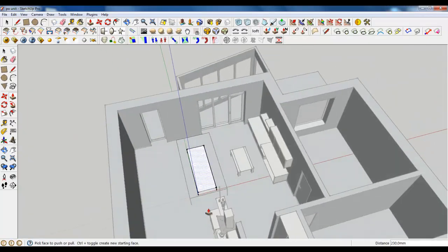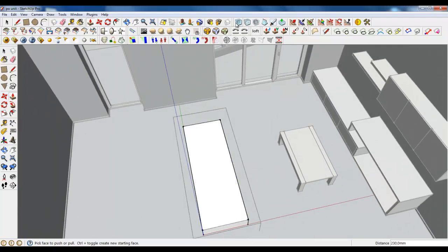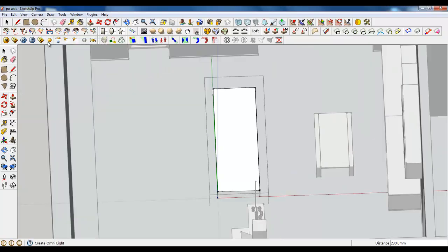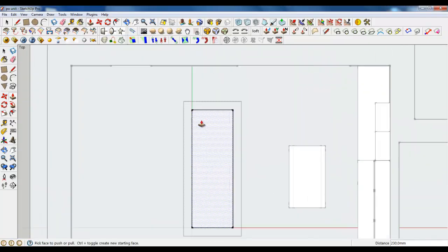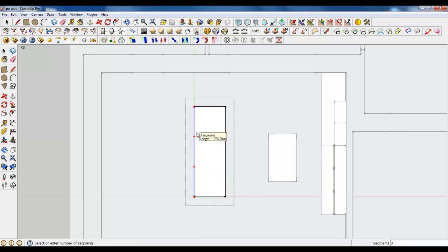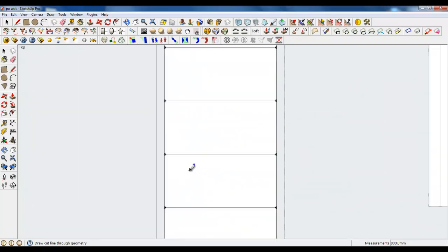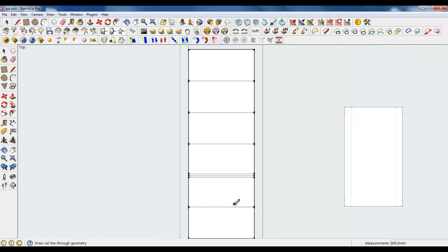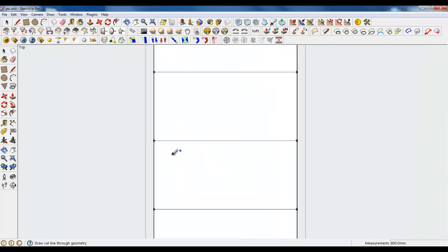And now we need to cut these faces. So we are going to use artisan toolset and knife subdivide tool. But before that, turn on this view and top one. Divide this line into 3 segments, and with knife tool cut it. Just take a middle point to cut it, and now zoom in and make this kind of cuts for this one line and this one.